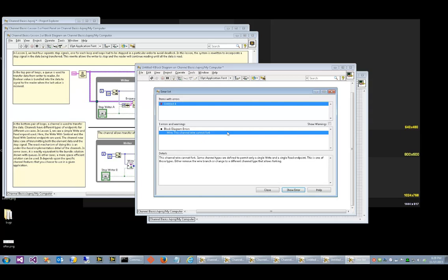And while we're not really taking full advantage of that in the compiler at the moment, that opens the door for us to do some significant compiler optimizations on the FPGA in particular. Oh yes, these do deploy on FPGA. And eventually we think we'll be able to do optimizations on the desktop that we don't do today, because we know one reader, one writer, and we can pair some things together.